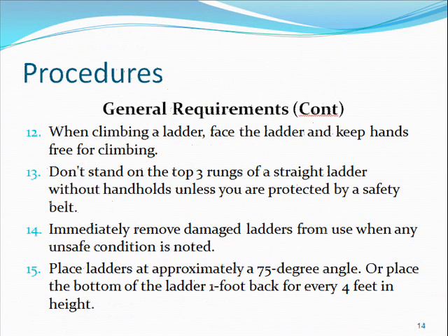When climbing the ladder, face the ladder and keep hands free from carrying. Don't stand on the top 3 rungs of a straight ladder without handholds unless they are protected by a safety belt. Immediately remove damaged ladders from use when any unsafe condition is noted. Place ladders at approximately 75-degree angle or place the bottom of the ladder 1 foot back for every 4 feet in height.